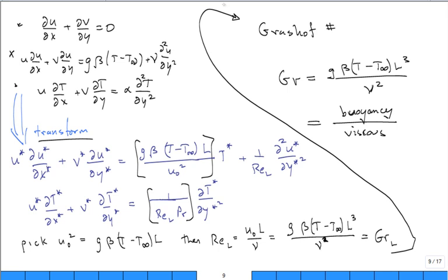And then you say, well, the speed squared is proportional to this term. Hence, you substitute for that term in the Reynolds number, and you pick up a new dimensionless ratio, and its name is called the Grashof number. We get a new number, it's called the Grashof number.